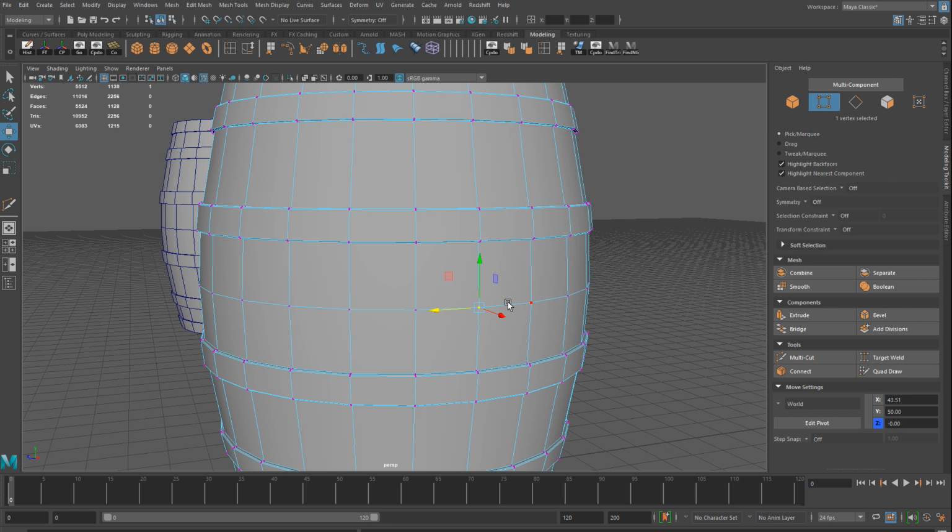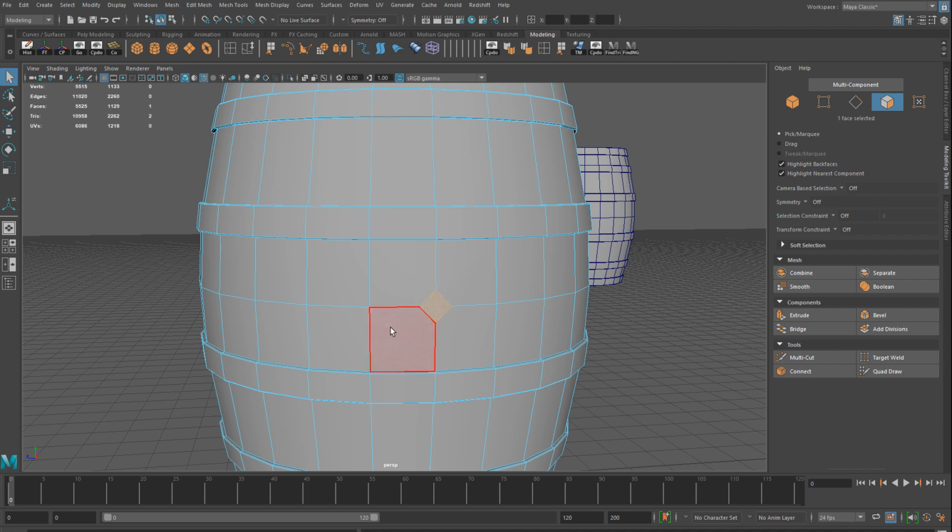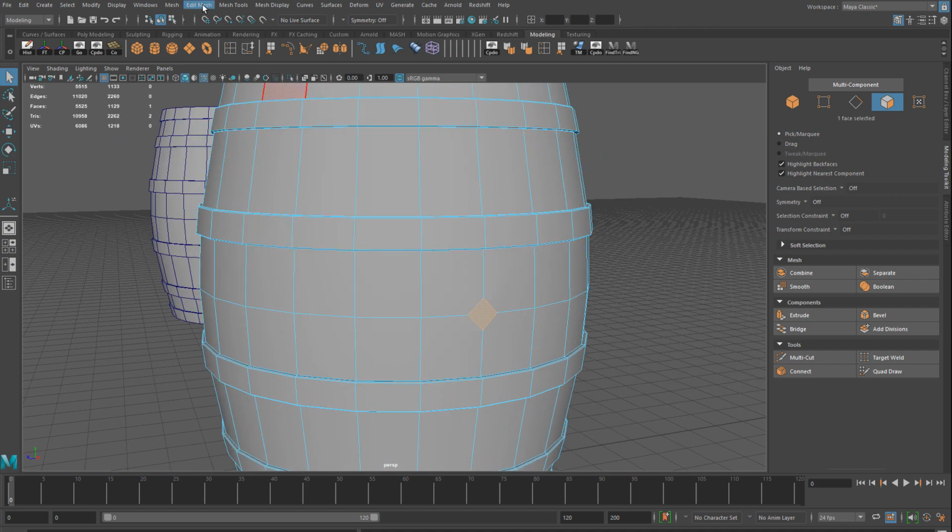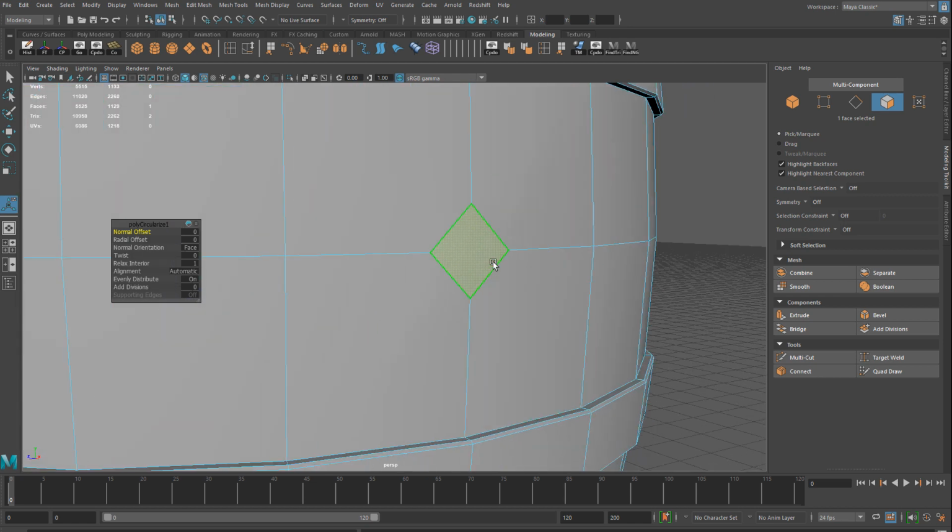I already have geometry here, and I'm going to select that one vertex, and I want to create more geometry to circleize. So when you have a vertex, select that vertex and then bevel it, Control B. This creates an area of geometry by splitting that vertex into 4 vertices. You can then select that face and go to Edit Mesh and Circleize. When you circleize, however, we don't have additional geometry in here to circleize. So you cannot circleize a quad. We need extra divisions. If we had more geometry here to begin with, it would circleize.